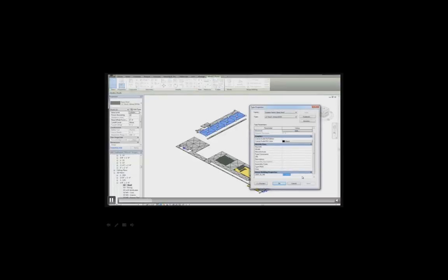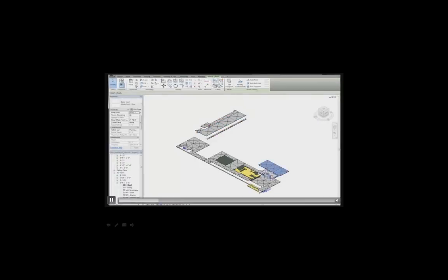It's a calculated value in the schedule. Yeah. And it's looking at the pitch that the roof is. What happens when one piece of roof has multiple slopes? You're going to model it as different roofs then, right? Just for this purpose, you'd have to model it as different roofs because you'd have to associate one as a steep roof and one as a non-steep roof.